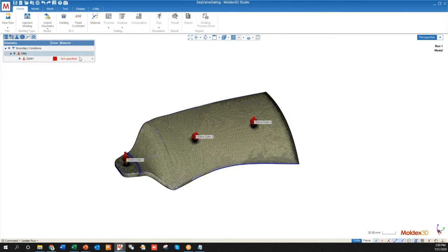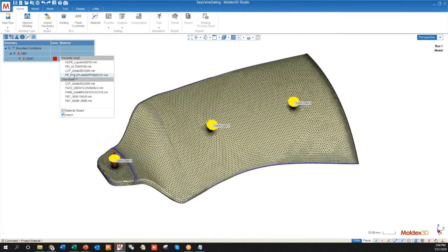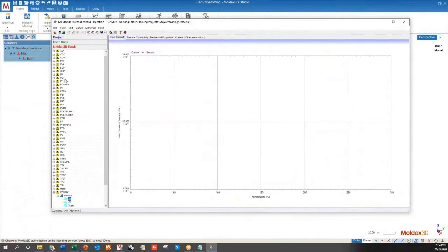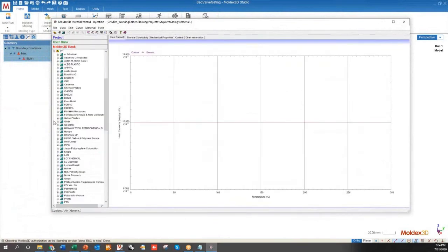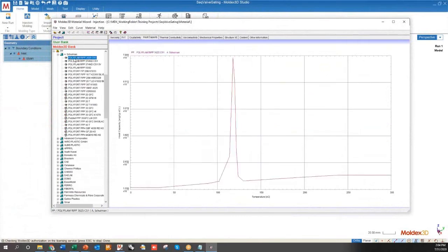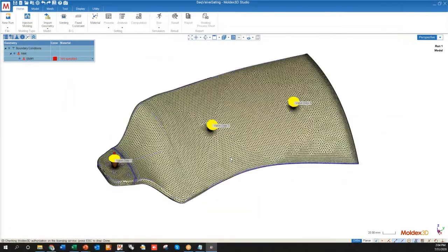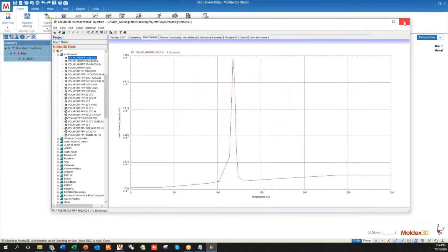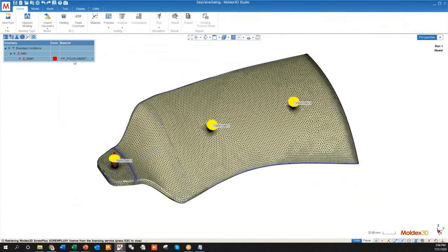All right, selecting a material. So I'm just going to be using a simple polypropylene material. You can actually go through the material wizard, and we can go to Moldex3D bank. All right, I'll find my polypropylene materials. I'm just going to use the first material under polypropylene from A. Schulman. I'm just going to double click on this material. That will add it to my project, and for my simulation you'll get this little prompt. You can press OK on this prompt, and then you can exit out of the material wizard,